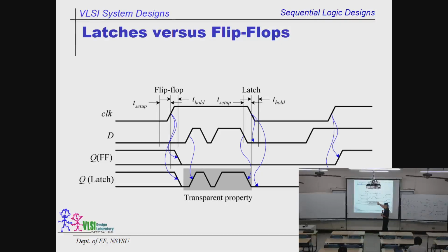Now please pay attention to the screen. If you are going to use a flip-flop, please watch this. This is a flip-flop, and this is a latch. A flip-flop only pays attention to the edges. It could be a rising edge, it could be a falling edge. This is the data. Data could change at any time. It could be any signal, high or low. We don't care.